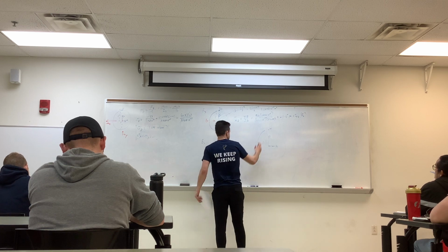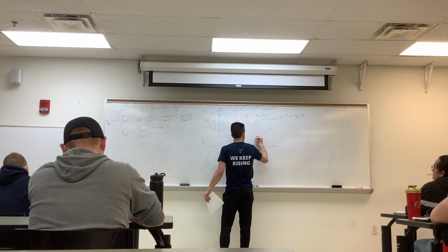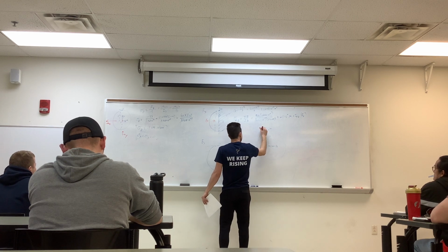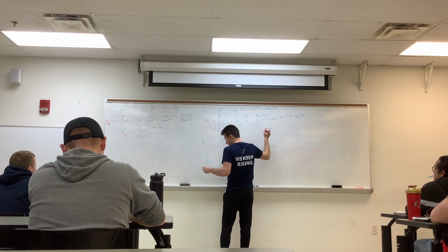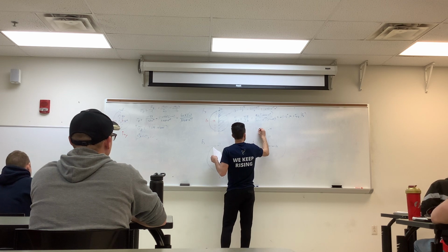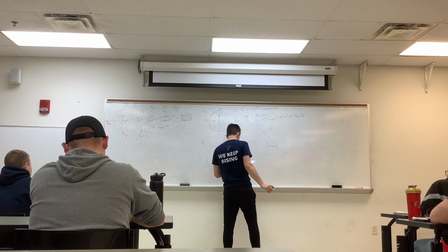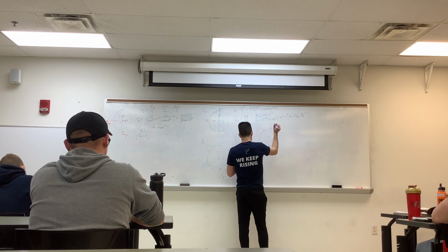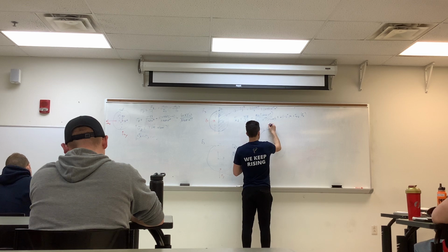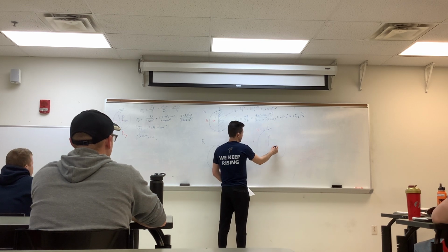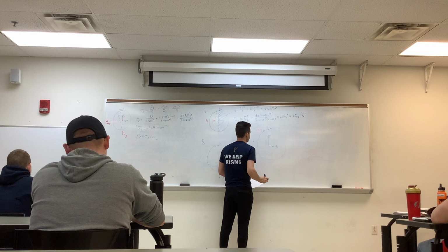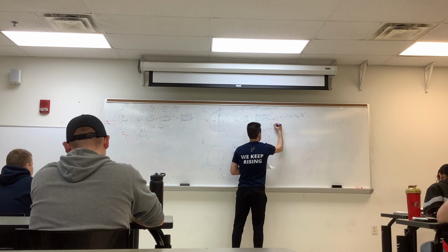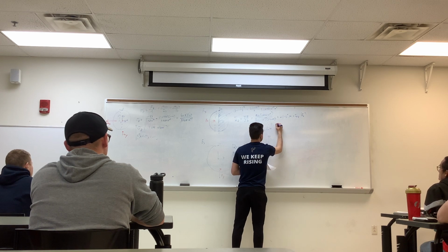This is our torsion, so as this thing twists, f of z at point H. The shear, when we talk about torsion, is acting negative to what our positive cross section is. So this is our negative tau xz.